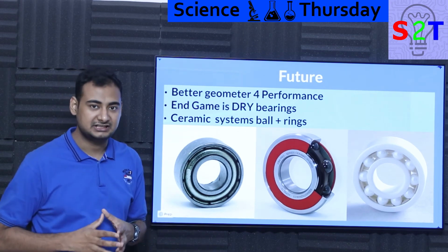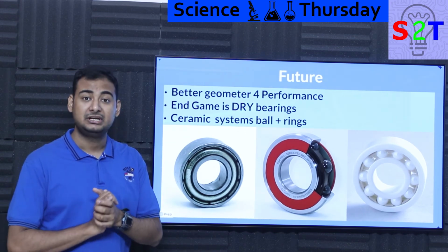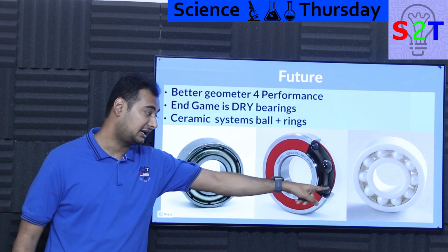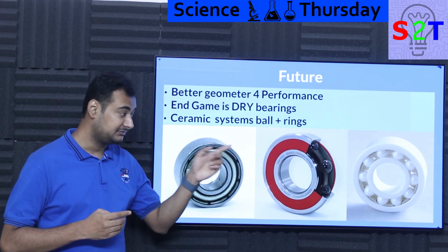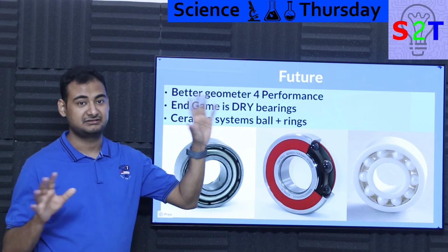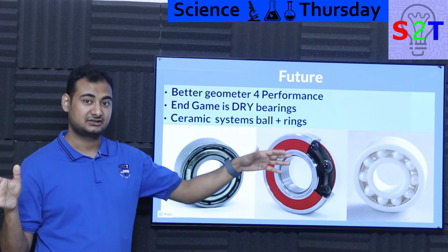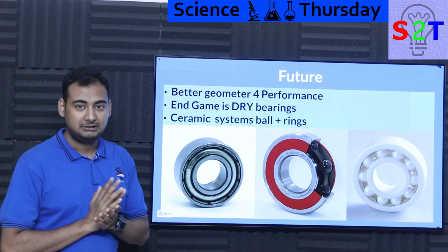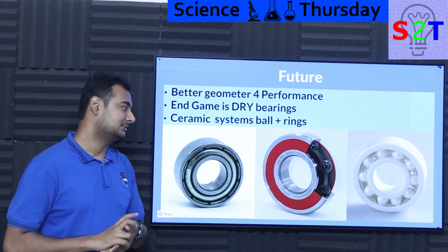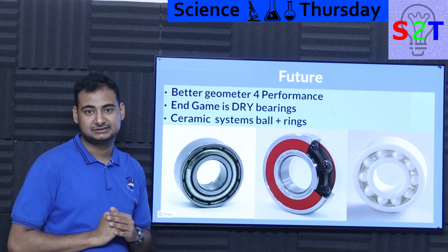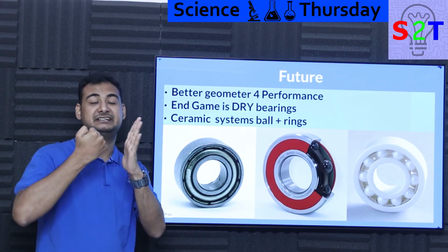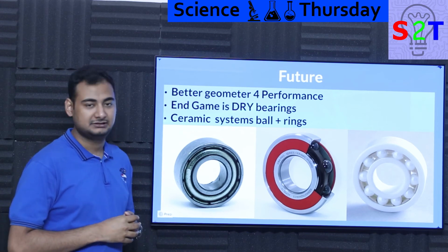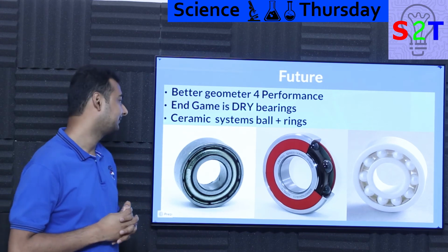For example, the clock that is being built by Jeff Bezos, the 10,000 year clock, would flat out not be possible if you were utilizing any bearing that has lubrication. So they are relying on ceramic bearings, and the same bearings are now being used in every satellite. Whenever they have solar panels that are shifting, or gyroscopes that are spinning, they utilize these, because space does have the benefit of not having any dust in it. So that's one good thing. And because ceramic is harder than steel, at the point of contact it has less deformation, which gives you a much longer lifespan, and your grease will not break apart due to cosmic rays. So that's the whole point.